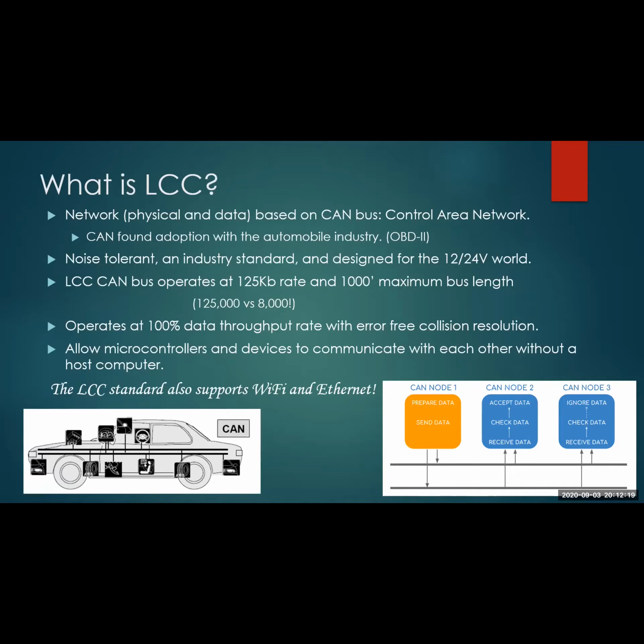address. Now, what's neat about that is for the modular guys, if there's modular guys in the group here, you're always worried about when you plug things together that you don't have address problems. Well, LCC set up that every node right out of the factory comes with its own address, so you never have to worry about that. Once you set it up, you just plug them together and they can talk without any errors. Kind of cool stuff.